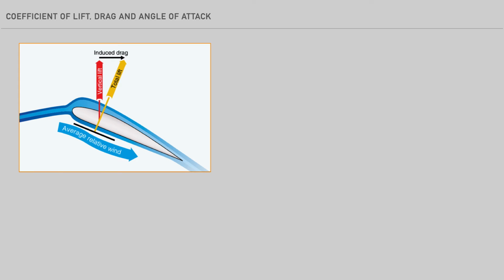There are two types of drag: parasitic, which is intuitive, and induced drag, which is insidious. Induced drag is the unavoidable byproduct of lift and acts parallel and in the same direction as the relative wind. Parasitic drag is composed of several types.